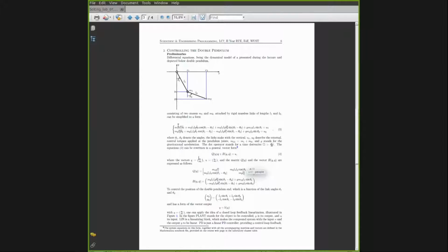And now we will change this system to be a control system, in the sense that we will apply two new variables, u1 and u2, which are our controls. We have already done such a thing also when we wanted to observe some excitation of the systems. So we propose that the system will have some controls. In our case, with this double pendulum, this control is nothing else but the torque which is applied at the pendulum joints. So U1 will be a torque in the first joint with the angle θ1, and U2 is the torque which we apply in the second joint θ2. So you can imagine that you have some electrical motors which drive your pendulum in this way, that the motors provide torques to the system.